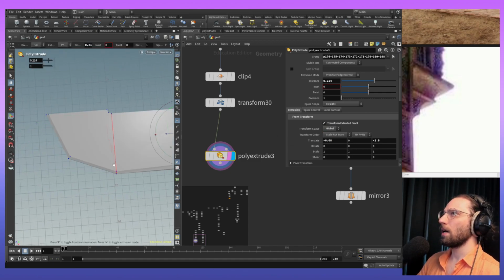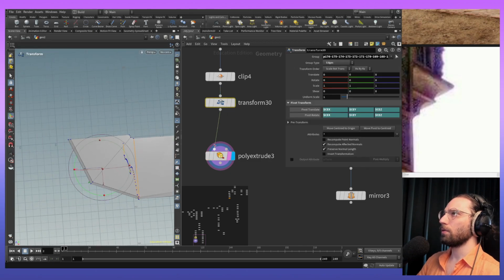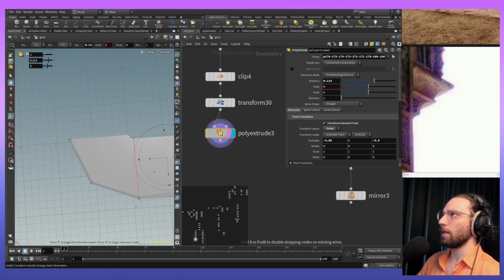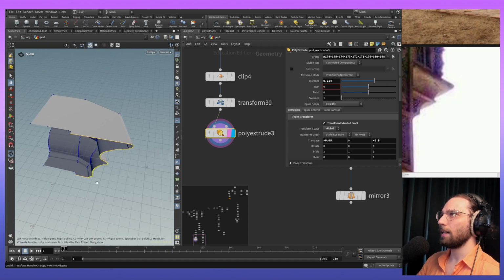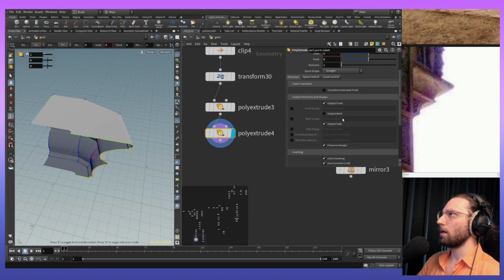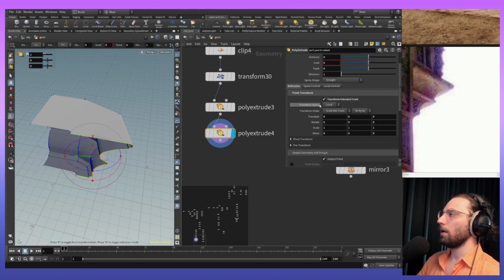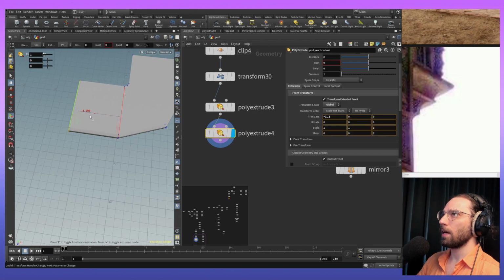Okay, that is at least a better setting for now. We will just go with it and see how that will change things. We'll do another extrusion. Obviously, we will. Okay, so we'll do it right from there. We will press 3 to select the edges, Shift A and click, and then tap that to get a pull extrude. And that one will also be, okay, so you have to press this first, and then you have to change it to global, and then you should be able to change that. Okay, this looks good.